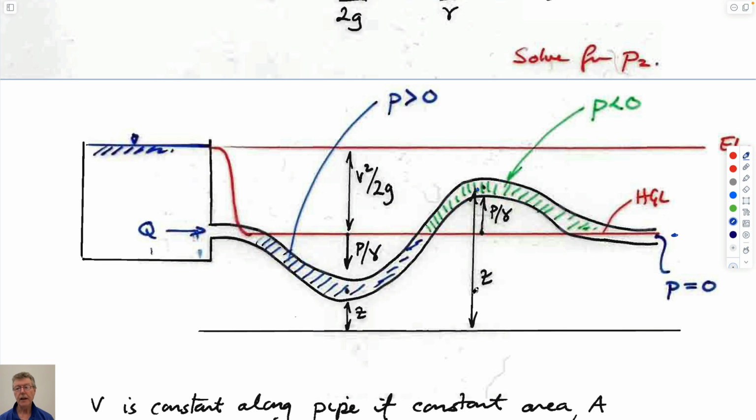we know that if you pull the pipe up here, the elevation here is Z. The pressure head has to go down because the velocity head along this constant diameter pipe has to be the same all the way along it. So this will be a negative pressure, or less than atmospheric. If it's much less than atmospheric, it'll reach the cavitation pressure, the vapor pressure for water, and we know that's about 30 feet. So if the pipe goes up 30 feet, the pressure at the top of the siphon will be at absolute 0, close, and it will cavitate. And it will pull the air out, and the air will gather in the headspace in the top of the pipe. That has been a good question on tests.